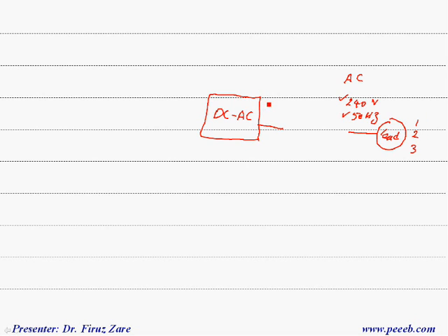But the point is that because the output voltage is based on a pulse pattern, in real time we have a PWM output voltage. This type of voltage in real time is not suitable for different applications. So that's why in this case we need to have a filter, and the output voltage can be a sine wave with a little bit of harmonics, and the harmonic level depends on the type of filter.